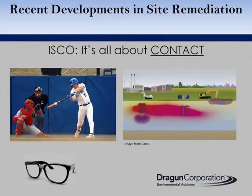We've gotten better in a couple of ways. As we learned during last week's webinar, recognizing that better characterization is needed for remediation than just a traditional investigation is key. We can now employ high-resolution site characterization, such as MIP, LIF, and HPT, which you would have learned about during Mike and Chris's presentation last week. And we can also attain more precise injection depth intervals using specialized injection tools. And we'll learn a little bit more about that in the next slide.